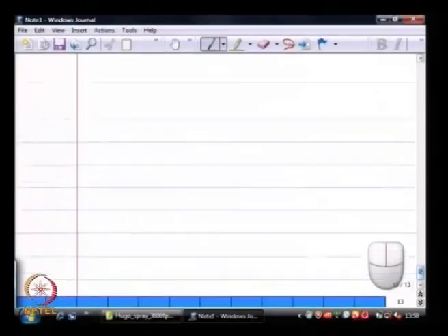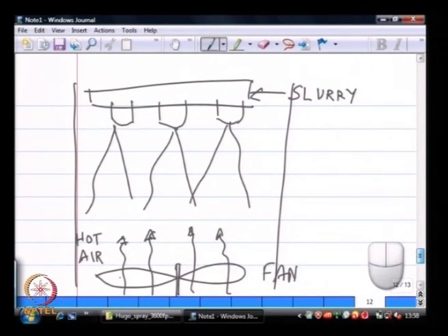So, whatever particles were in a single drop now agglomerate to form a cluster, which gives you the feel of coffee granules. You can take a single granule and crush it and get powder, but if I sold you powder, it would not taste as good as granules. Okay, so, this is the process by which most granulated powder materials are manufactured. Spray drying is very efficient. You are talking several thousands of pounds per hour, extremely high flow rates, and several nozzles, because productivity and production rates depend on that.